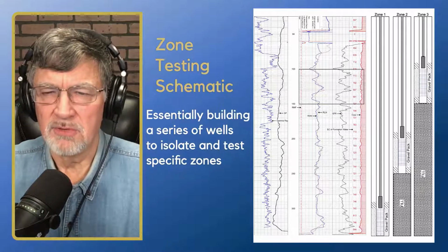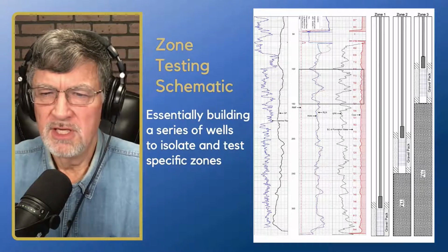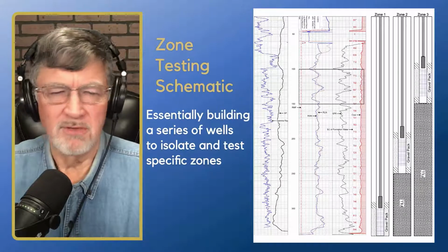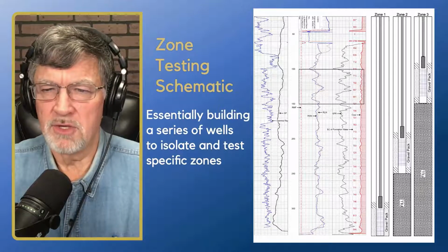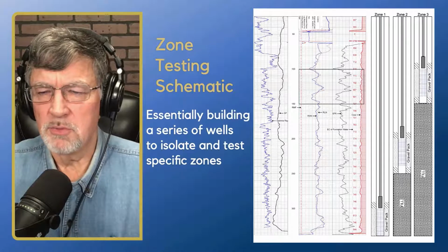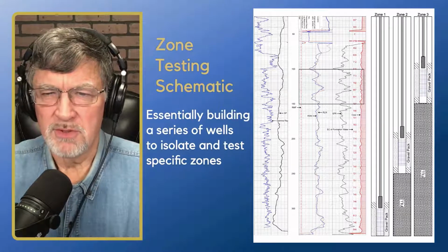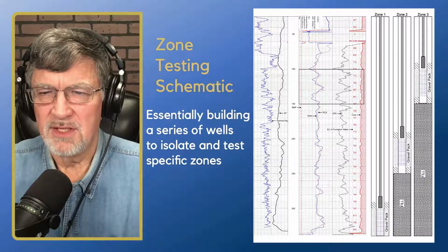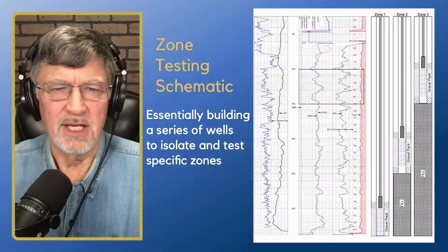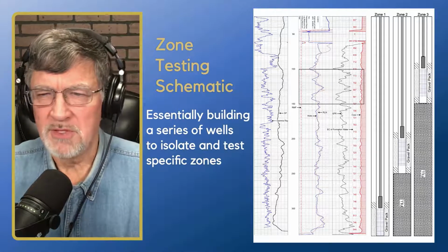You can see on the resistivity, so that's the farthest right of the geophysical logs, we got a bump in the resistivity that indicates we probably have a decent water bearing zone. So we wanted to go in and test that. And then what we do is we put fill in that zone, and then we go up to the next one. So there's a zone in there from about 200 to 250 that we'd want to look at isolating and test that zone.